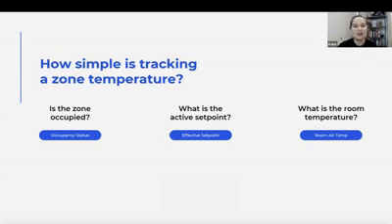So when you are looking at a fault for a zone being above or below set point, the reason this is a nice fault to have is when you're looking at a campus environment, you all know this, you have thousands of zones everywhere. And being able to track whether they're all in compliance is a very difficult task. You're really, for the most part, waiting for a comfort call. You're waiting for the occupant to be uncomfortable enough that they will call into your work control center. And so this is a nice fault to have, because you can see all the zones that are out of compliance on my campus. I know how far they might be out of compliance, and I can go hit the big hitters.